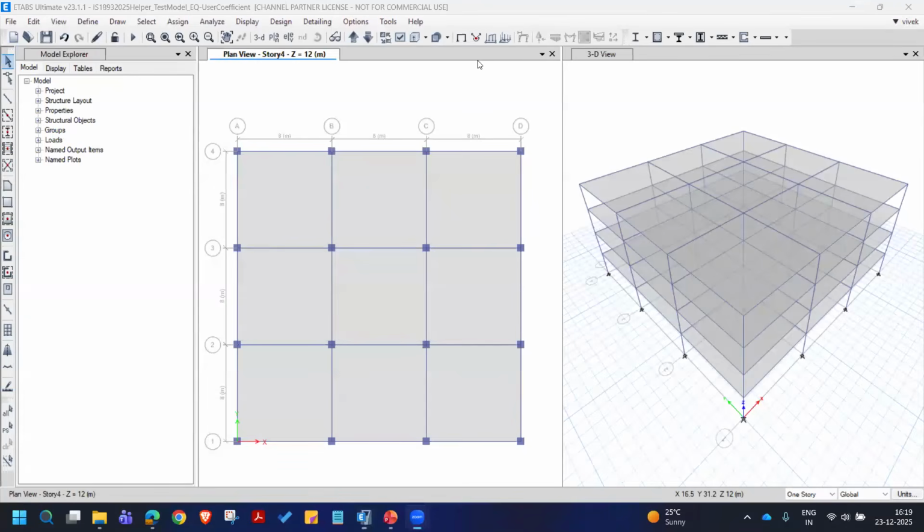Yeah, combinations. This again needs to be combinations. I'm sorry, combinations for the projections. So these need to be separately defined and used only for that member design, not for the main structure. So we'll have to handle it that way. You can define combinations with the required enhancement for the seismic and then use it for the design of the members for one iteration of the design and then get that value for detailing purpose. That is the only way to go about it.